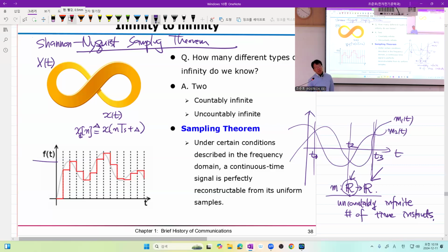So this theorem actually starts from this. You have a random process, not a deterministic signal. Now it is strictly band limited. Then your uniform sampler, if its sampling rate is greater than or equal to twice the maximum frequency content of this random process, allows you perfect reconstruction of your x of t. So x of t can be perfectly reconstructed.